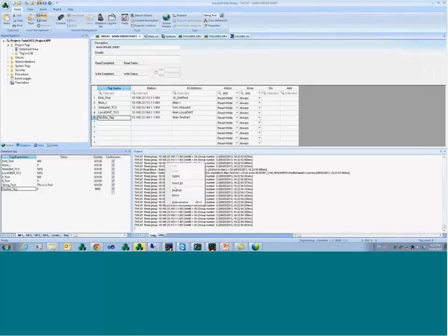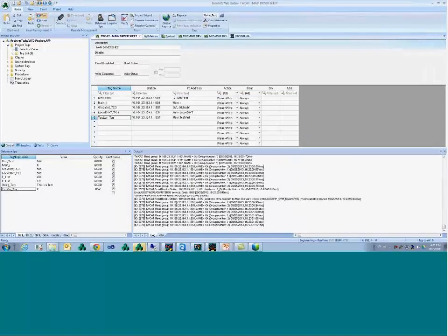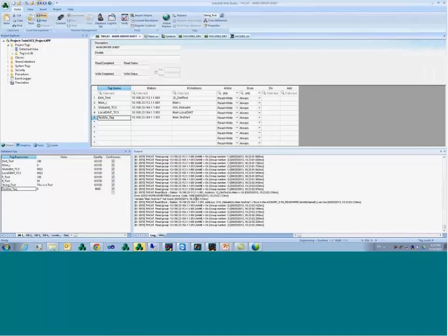And if you look on the output window, if you enable the protocol analyzer option, it's going to show which tag was not found. Okay, so this variable called main.testvar1 was not found. I need to go back, look on my driver sheets, and fix it. I save it.